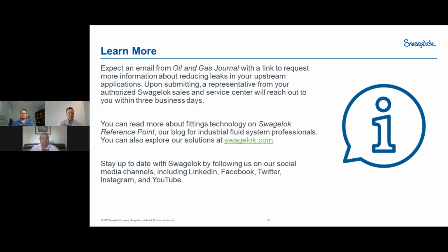So there are some resources that Swagelok's got out there. The full Tube Fitter's Manual has a couple tables. There's a pocket guide that I think contains the same. And really the recommendations are based on tubing size. So 1/2-inch tubing every 5 feet, 1-inch tubing every 7 feet, right? So it depends on the tubing sizes.